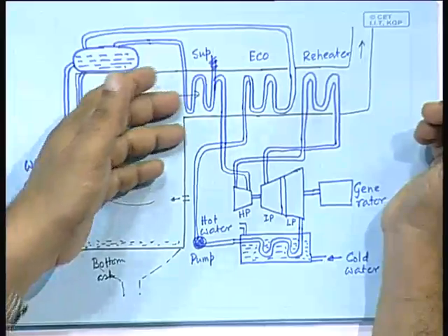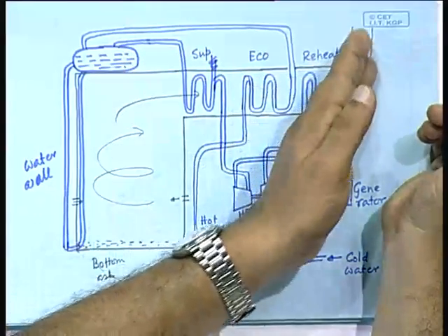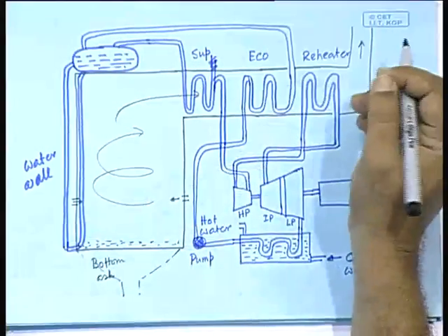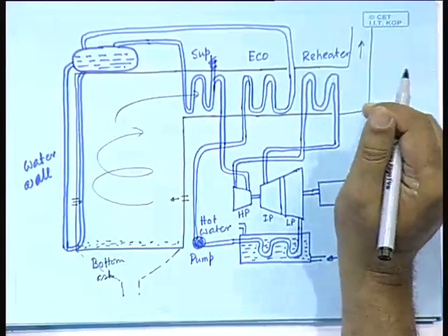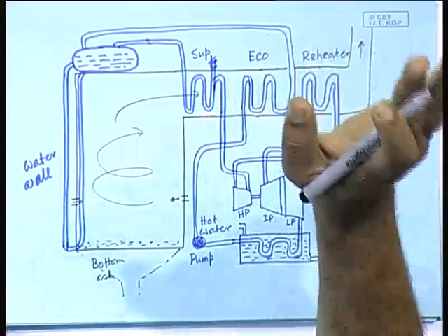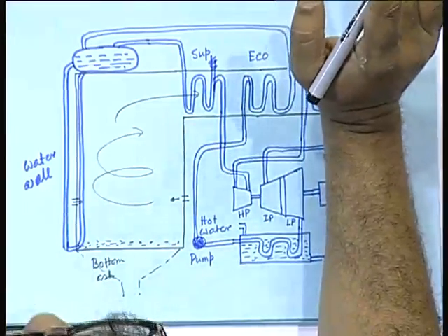It is the ash that flies, called the fly ash, that is the main problem. The fly ash goes along and finally finds its way along the chimney. So, something has to be done to that. Fortunately, now we have reasonably good measures to arrest the fly ash, that is called electrostatic precipitators.